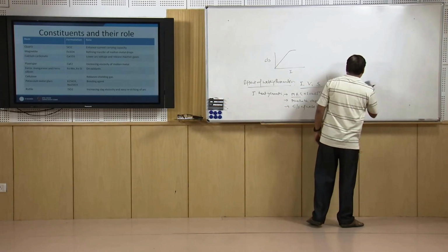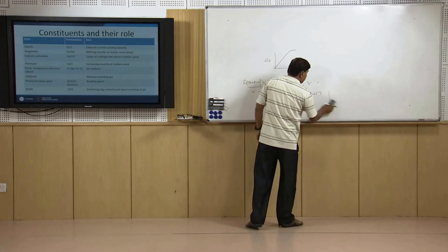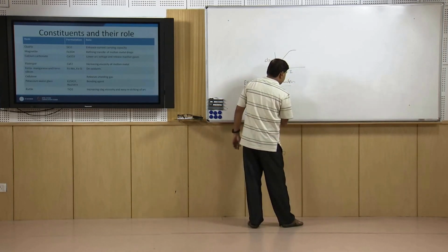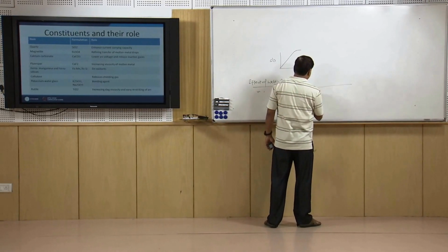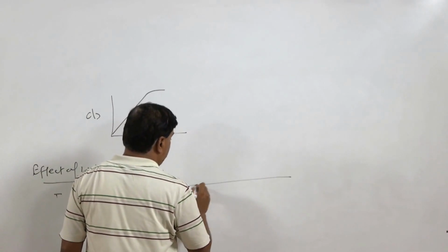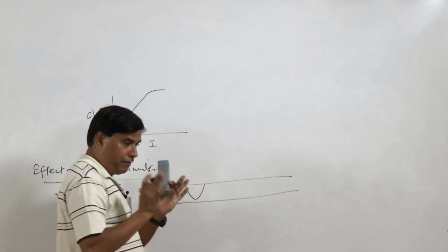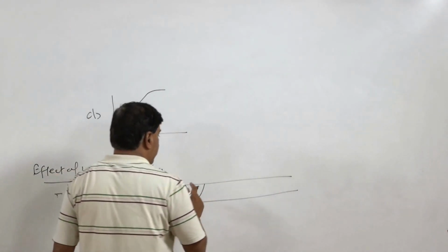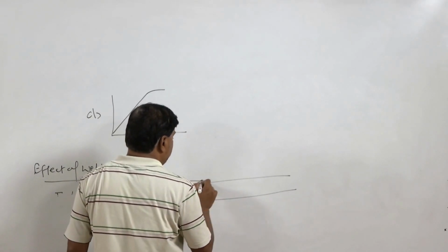The welding speed directly affects the amount of heat being delivered to the base metal per unit length. If the speed is very low, then heat will be delivered continuously over a small area and it will result in a large weld cross section. Depth may be limited, but it is very wide.